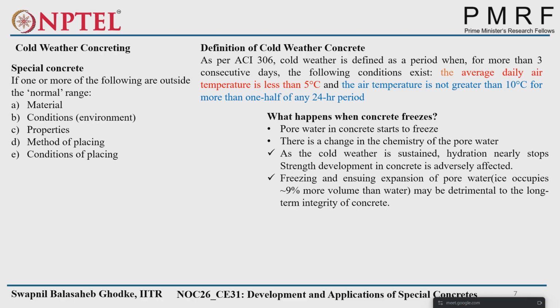So strength development in concrete is adversely affected, because most of the strength comes from hydration, from the hydrated product, calcium silicate hydrate. That gives most of the strength of the concrete.